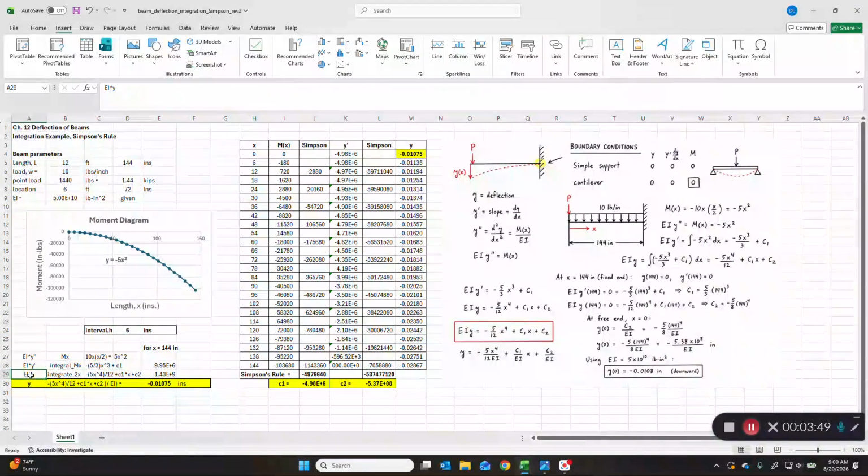And then if we're integrating it a second time, we're getting EIy. We want y from this. If EI is a constant, we can parse out y, and that's the deflection at the tip, which is what we want. So we want these constants. How do you get these constants? These are the equations. We've just integrated by hand here, simple power rule integration. So we want the constants, and then we want the solutions to these two equations, EIy prime and EIy.